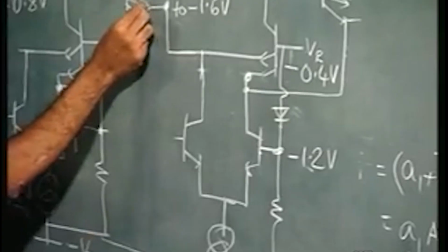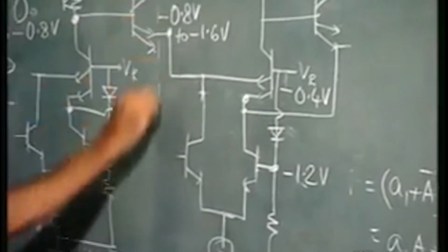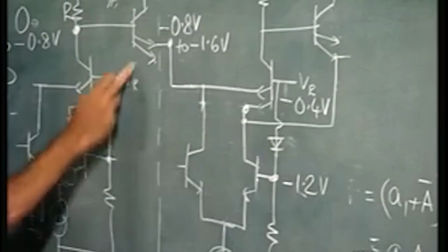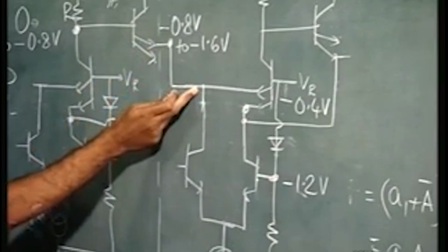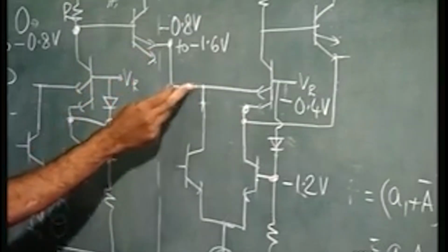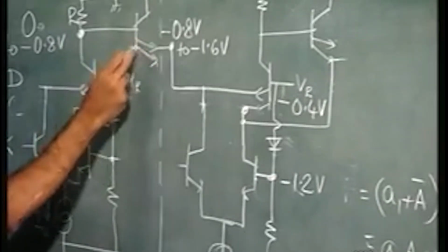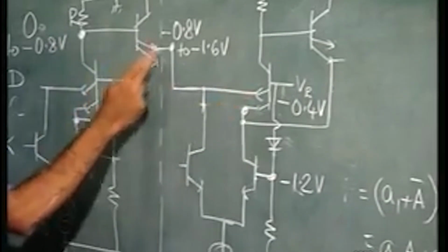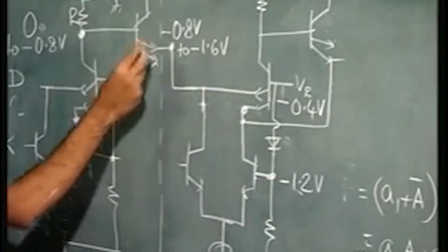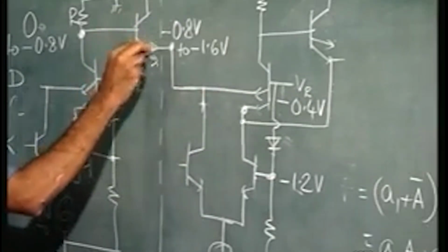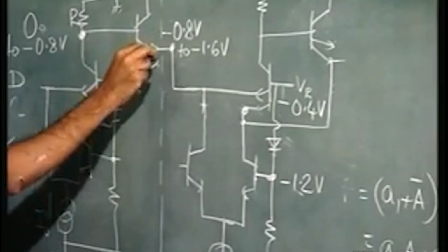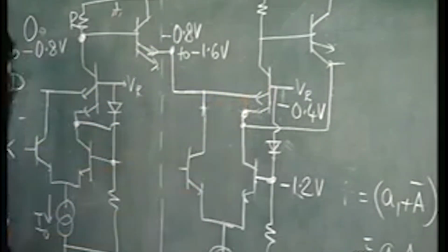When the output of a particular gate, so this is gate 1, is fed as a direct input here, what happens? Now, you again have an emitter coupled structure here. The output transistor of gate 1 and this transistor form an emitter coupled structure.